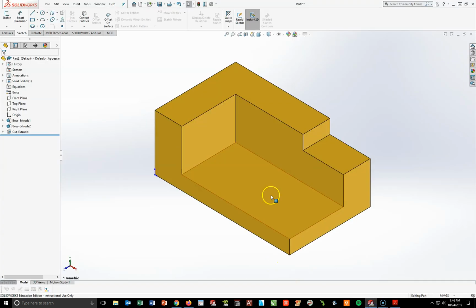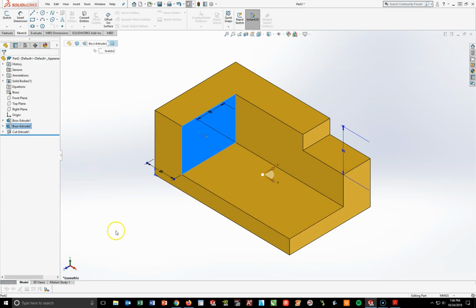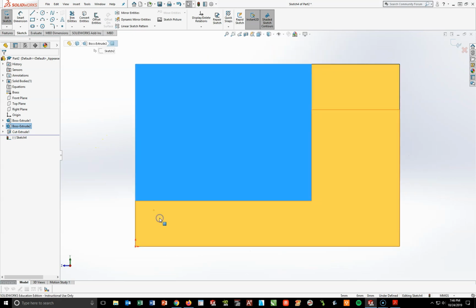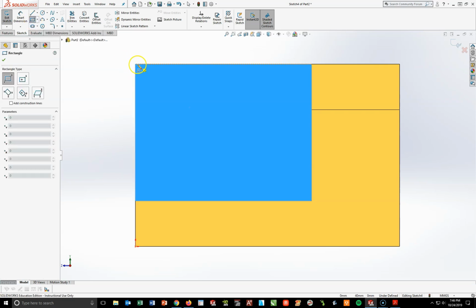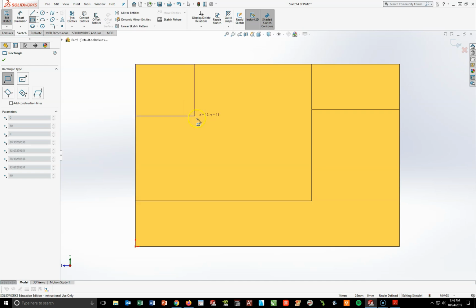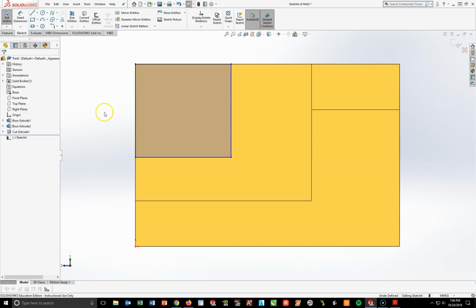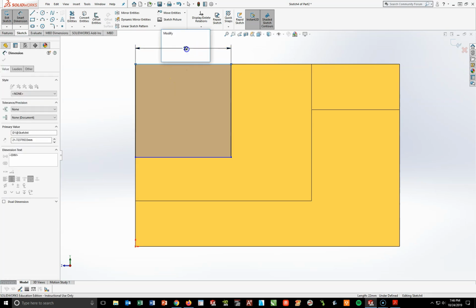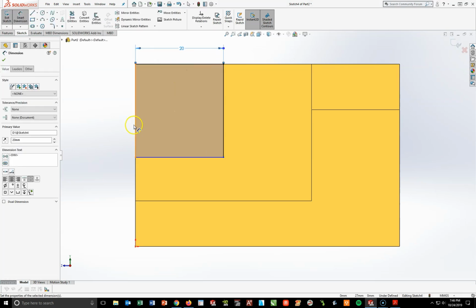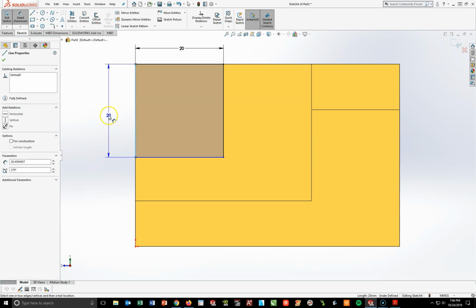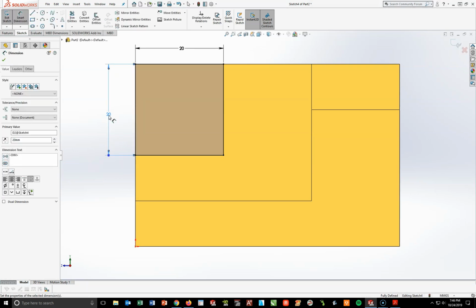So going back to SolidWorks, I'm going to highlight this face here. I'm going to start on the sketch toolbar, a new sketch, hit my space bar, and do Normal To. I'm now going to turn on my corner rectangle and lock on that corner. You'll see a little orange dot pop up. Pull down and left click. I'm going to hit escape to turn my tool off, and then turn on my Smart Dimension to make the top line 20. And this left line here, left click again, 20.